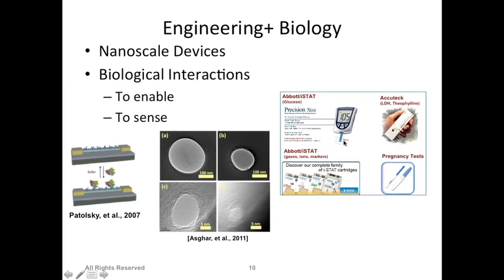And actually this strip is just electrodes. There are some electrodes already printed with a micro fabrication technology. So you make those electrodes very small because you don't want big electrodes, and you also want to make sure that you have control on their dimensions every time you get a similar device.